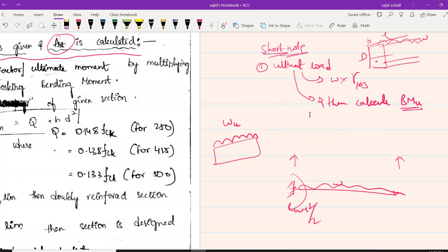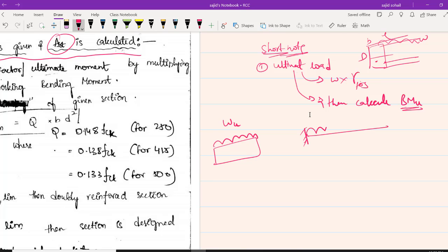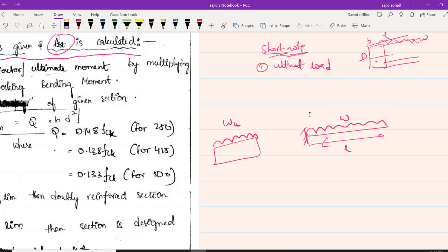See, some people might not have completed structural analysis or SOM. So let me tell you how to calculate once. See, this is not RCC part, this is structural analysis or common sense wala part. Okay, so if you have W, what is the total length? It is L, right? So how much is the total load? W is kilonewton per meter. इतना kilonewton load add कर रहा है per meter. It is UDL load. So if you are multiplying with the total length, what you will be getting? You will be getting total load, right? Meter cancel, and you will be getting WL kilonewton, which is the total load. So this beam is symmetrical to what?